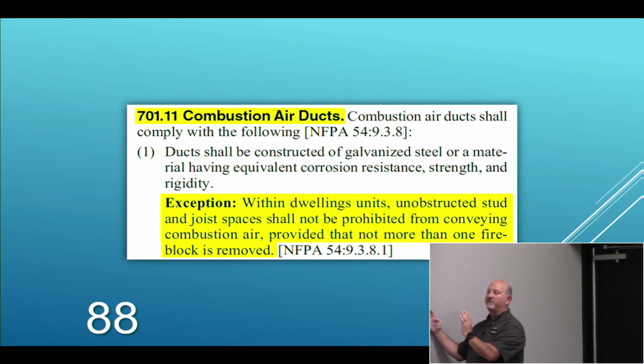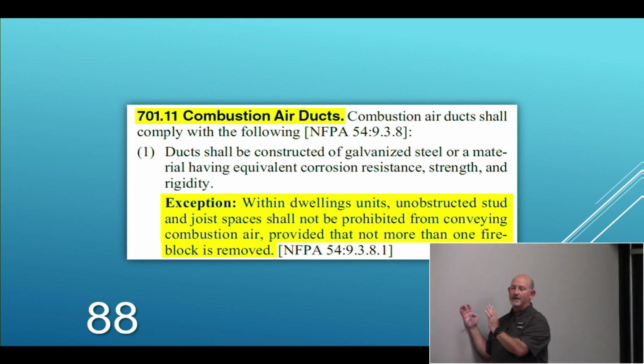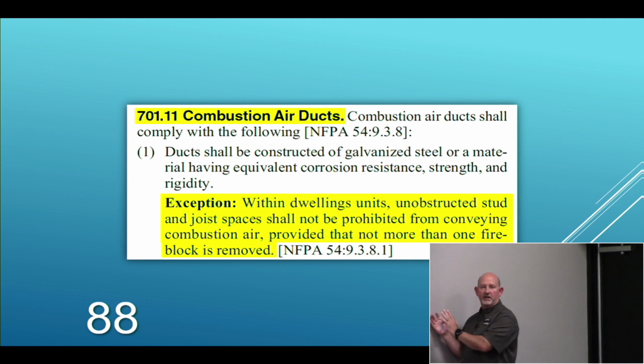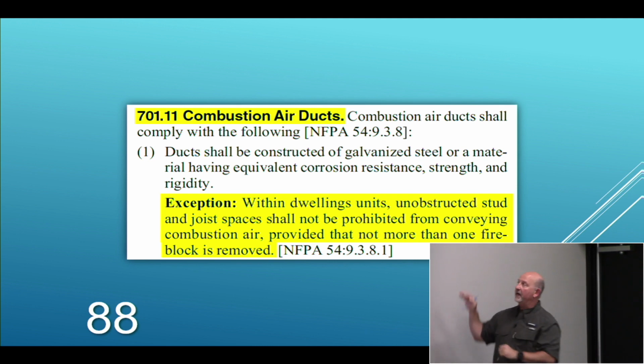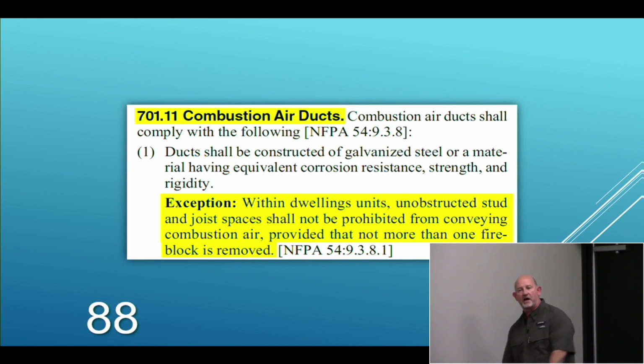Now first off, if this wall is full of insulation, do you agree it's obstructed? Right? Can't do anything with it. But if there's no insulation in here, for example, then I could take that one fire stop out. I could take my top plate off, let the air come in, let it come in here, cut a hole in the floor. That could be my lower.